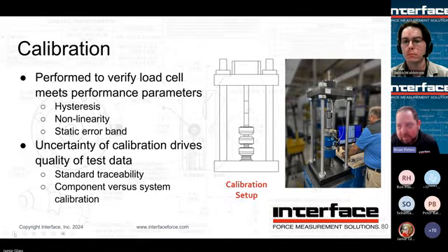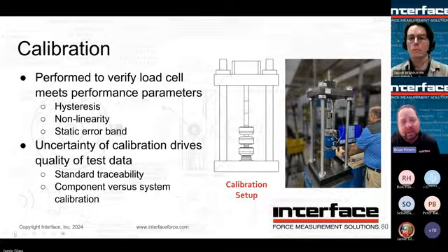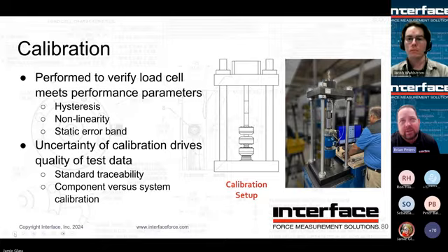So if you were to have two scenarios, one being very localized thermal changes that can impact the load cell's ability to respond properly from a temperature compensation standpoint, or if you have the scenario where you have a thermal gradient being introduced, say, through the load string, that may take time. Again, if the load cell doesn't stabilize thermally, then yes, you could have some less than complete thermal compensation happening from a bridge standpoint.